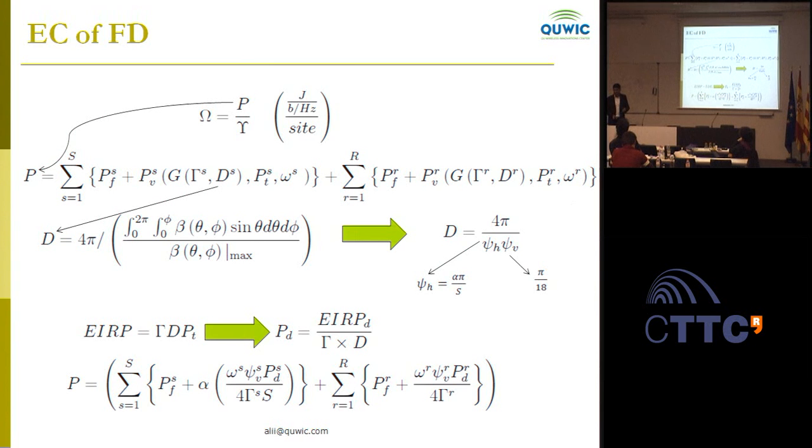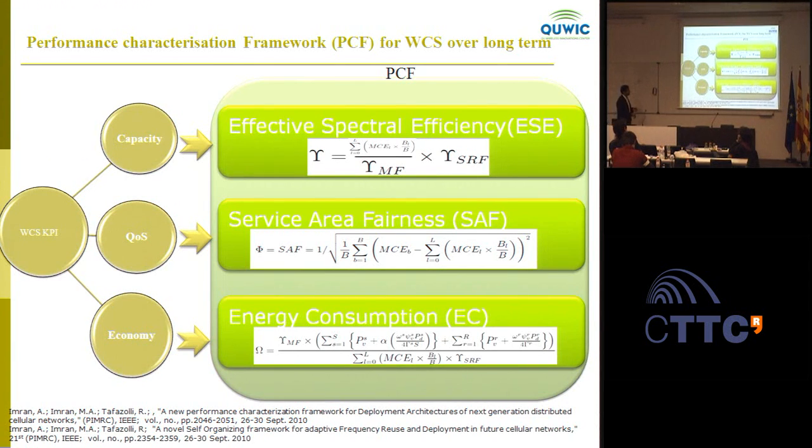Area spectral efficiency is good, but it has one problem, particularly with the advent of, we had this discussion on how to define spectral efficiency. This top expression you can recognize as the spectral efficiency we calculated, how the base station can determine it based on the CQI of users. But in the denominator there is a multiplexing factor. MF is the multiplexing factor, which is there for relay stations. When you have relay stations, you gain some area spectral efficiency because of better coverage, but you lose because you are multiplexing with them. To take that into account, it's in the denominator.